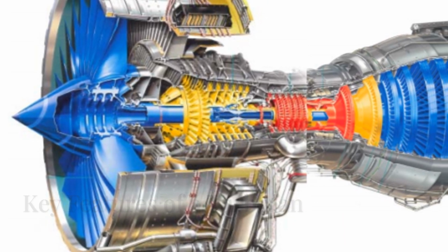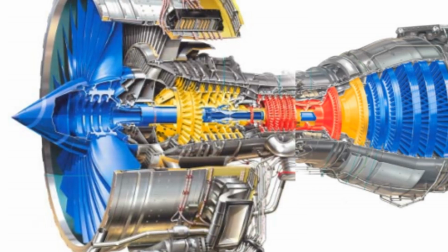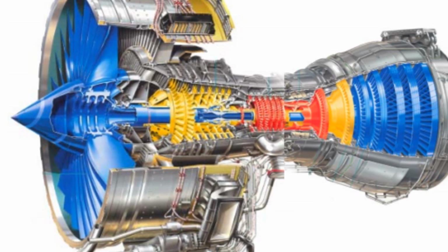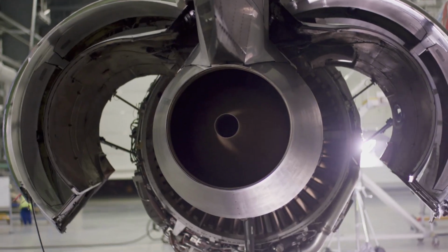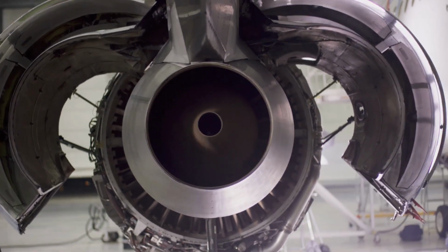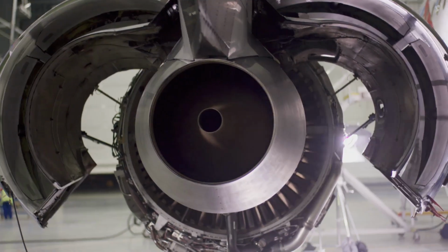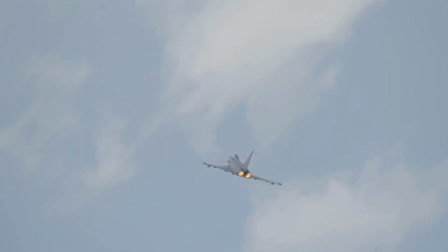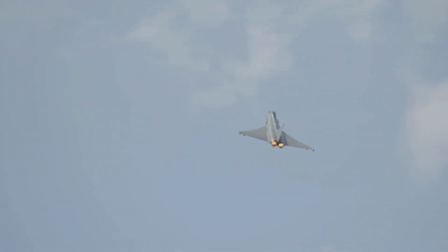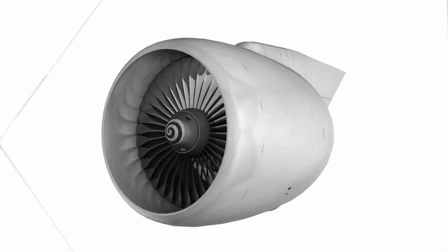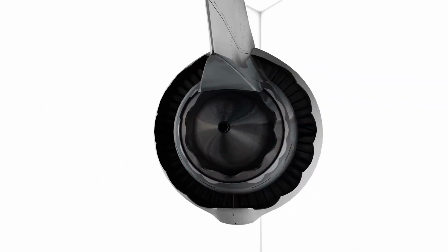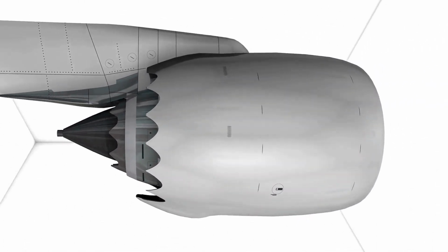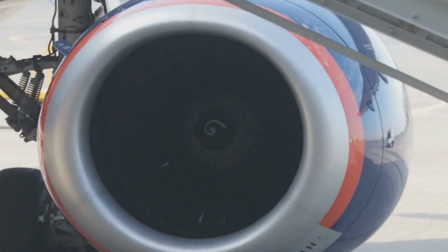The key features of a turbofan: bypass ratio. This is the ratio of air that bypasses the core to the air that goes through it. Modern airliners use high bypass turbofans, 6:1 or higher, for high fuel efficiency, while fighter jets use low bypass turbofans for high speed and thrust. Noise reduction. The cooler, slower bypass air surrounds the hot, fast core exhaust, which helps to reduce noise emissions compared